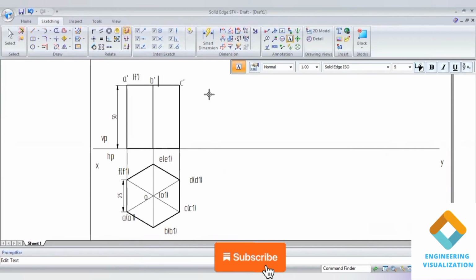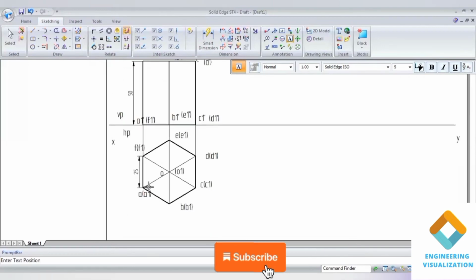So from the front view, A dash, B dash and C dash are visible; D dash, E dash and F dash are not visible. Not visible means we should write them within brackets. In the same way, for the bottom face we write the same thing. So now we need to copy the same diagram using the move command.